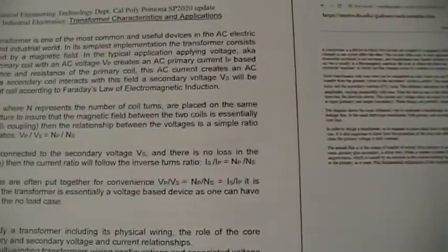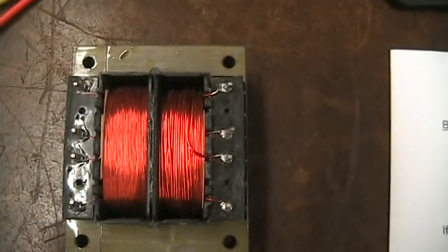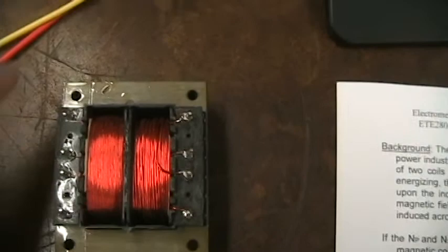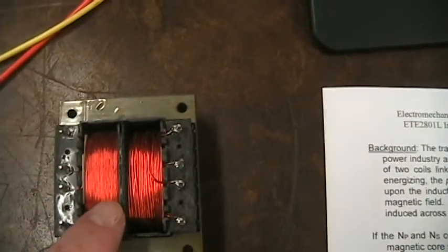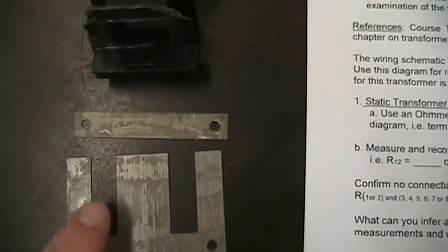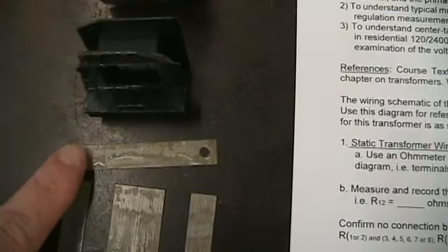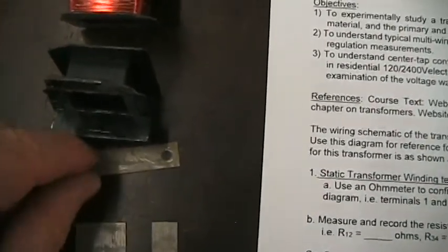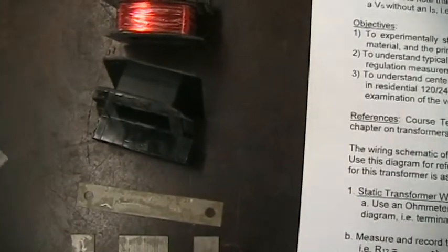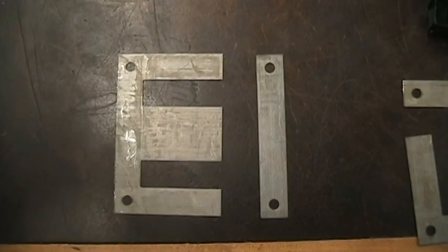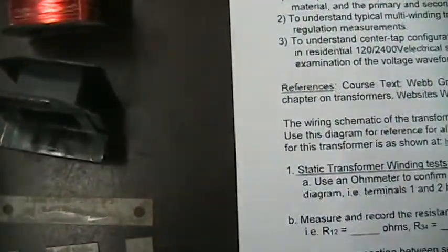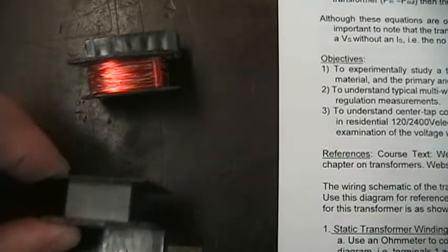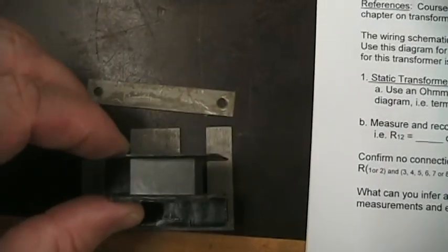The transformer itself, if you look at it closely, and we looked at it in class, we notice there's the metal parts and then the windings. If you took that apart, you'd see that the metal part is actually separated into two parts. We often call these the E and I core because it looks like an E and I core if you turn it on its side, right? And that's how the unit is put together. The bobbin, which holds the wire, sits inside of the transformer.